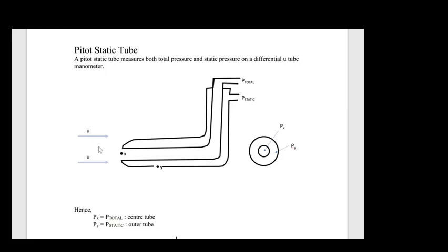However, because our fluid has 0 vertical component, Y here, this inlet here, is only measuring static pressure. There's 0 dynamic pressure. The fluid flowing in this direction does not contribute anything in terms of the dynamic pressure because there's 0 vertical component. Okay, so on the tube on the outside here, we've got 2 concentric rings. If you were to look from left to right from this position, what you would see is 2 concentric rings.